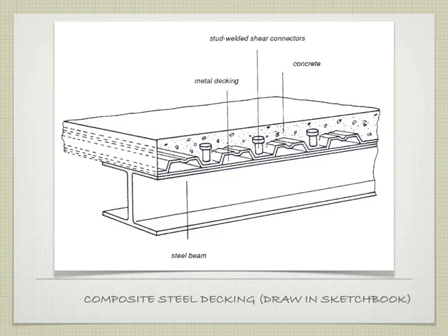There's actually a whole machine that does this, right? And it welds through the decking into the beam itself. And this then provides a nice tie point for the concrete topping to tie this whole thing together. This one's obviously a bit tall because it's sticking up a lot taller than it would be, because we'd want adequate cover in this particular decking. So that would be too much concrete in this example, but you get the idea of the shear stud and how it works.